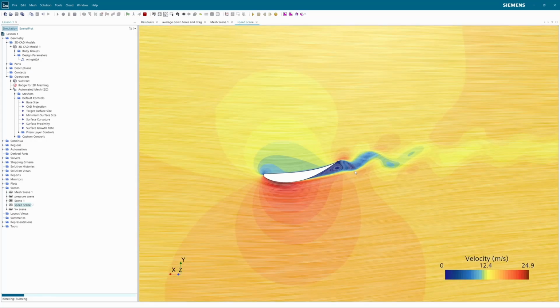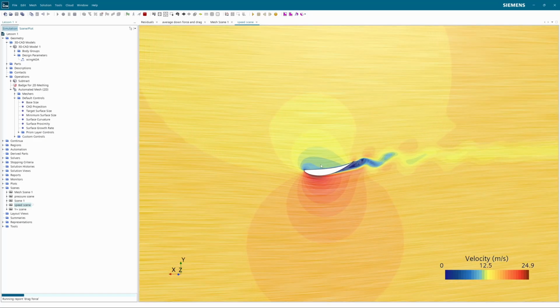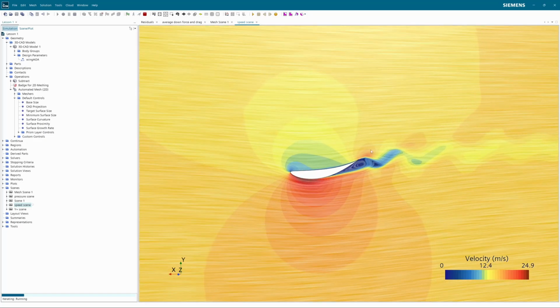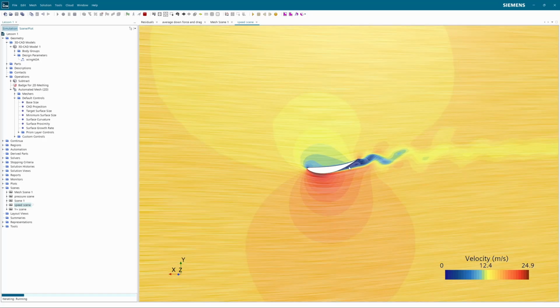Here you can still see this periodicity is due to this rhythmic vortex shedding that is happening over here. It is the same always, but it definitely does have an impact on the wing. This is not behavior that you want to have. So consider if we lowered this wing's angle of attack, this behavior would go away, of course.